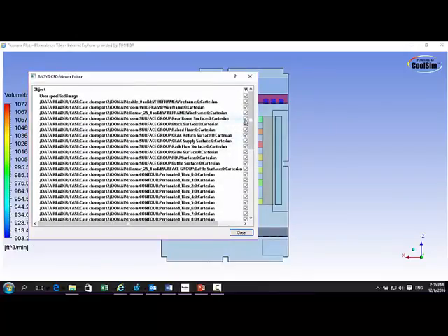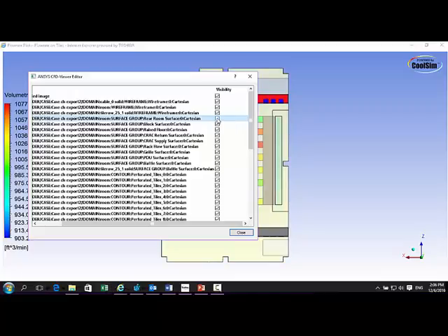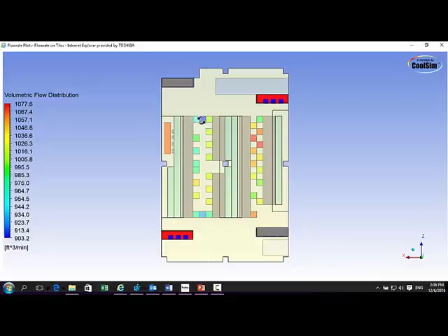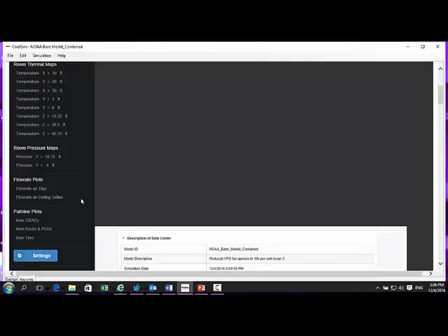So here you watch, I'm going to turn off the room surface. It makes that image clear. And now I can see it a bit better. So here are my outputs. And you notice that it's fairly dead in the middle of this room. See, this blue right here indicates that I'm fairly low in total flow through those tiles. Over here I've got a problem too. Again, this is because the air has come over and basically dissipated by the time it gets to the end. This one is going quite strong here. You see good flow pattern there, but as it gets towards this end, it drops off too. So not very good flow rate from that system.